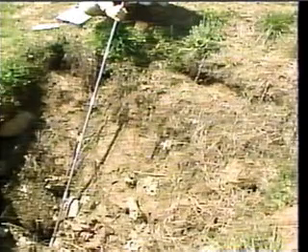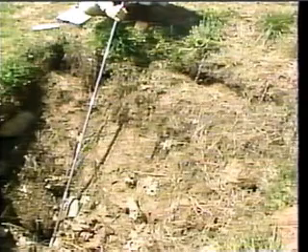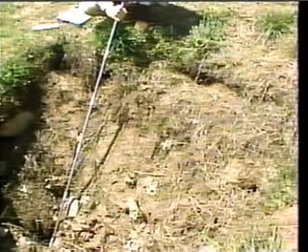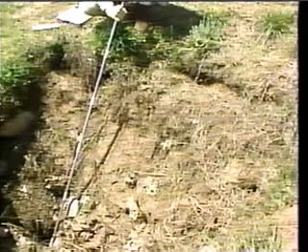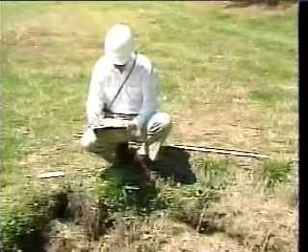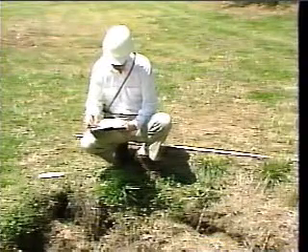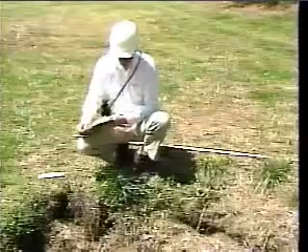A sinkhole is a very serious type of depression. Remember, it's caused by the removal of subsurface material. Then, the overlying material collapses into the resulting void. The presence of a sinkhole can be alarming. It may indicate piping. Possibly failure of the dam may follow.